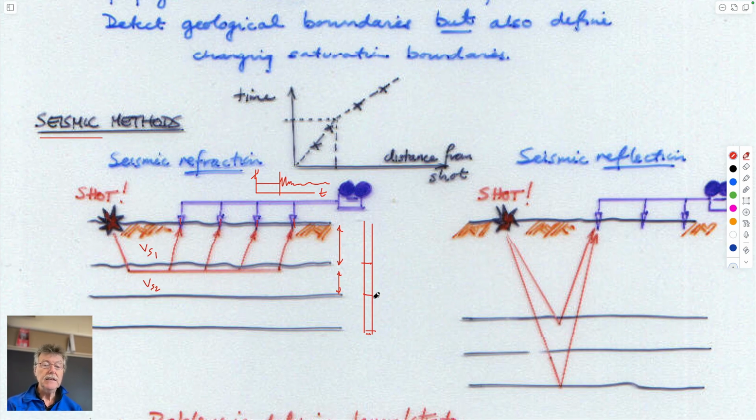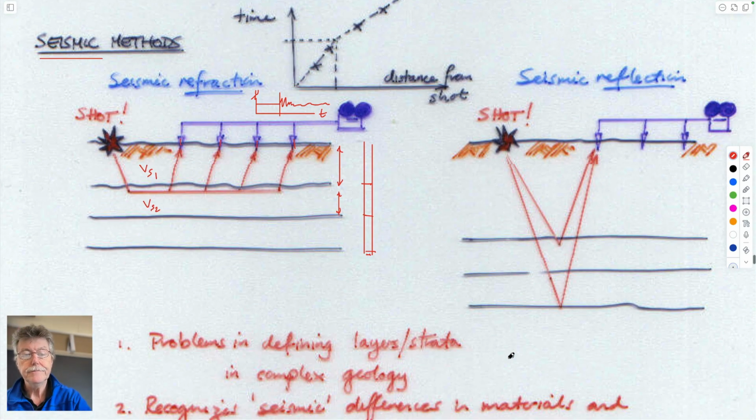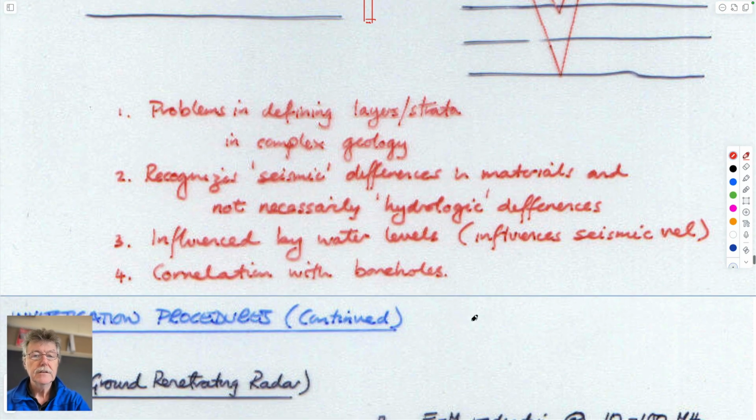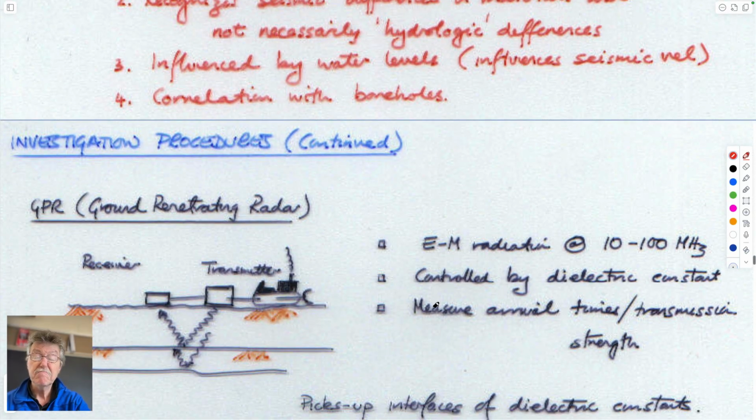This gives you great detail at a single point because you get a sample back or you get drill cuttings. This gives you a little detail inferred over a very large volume of your site, either by refraction or by reflection. And so that's the idea of doing that. So the idea is to define the stratigraphy.